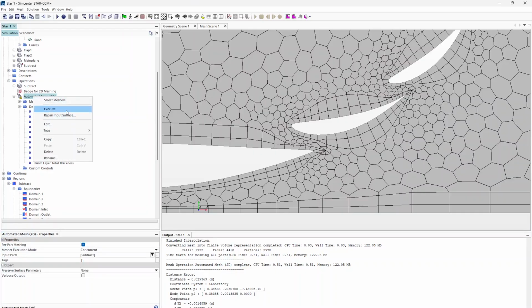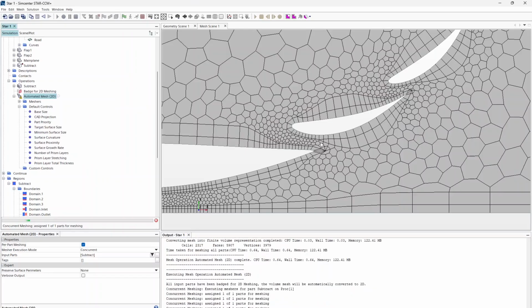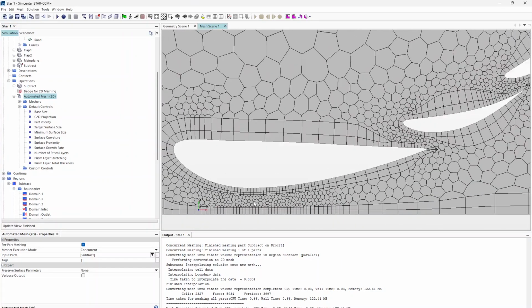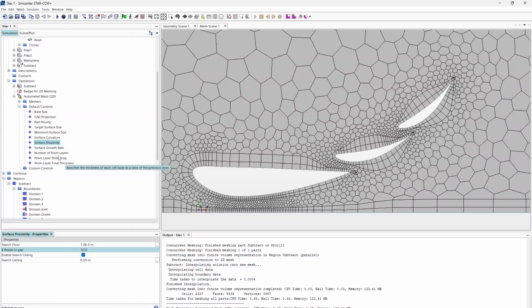So now when we execute, instead of just seeing a couple cells in between here, we should see more. And we did. And if we wanted even more than that to analyze the flow in between, we simply come back to proximity, we can do 20. And it should get even more cells in between. And it's not cooperating, that's great. It is cooperating down here to some extent. But anyways, we'll turn that back to 10, because that's actually what I normally prefer to go around.